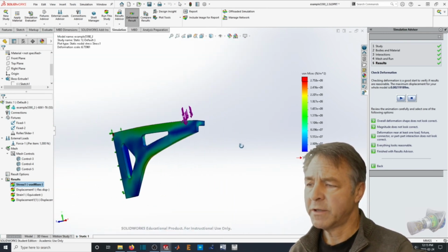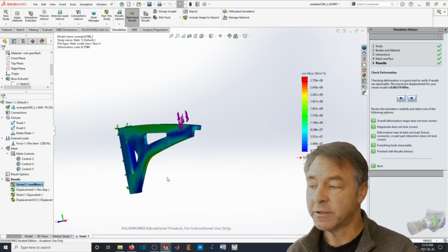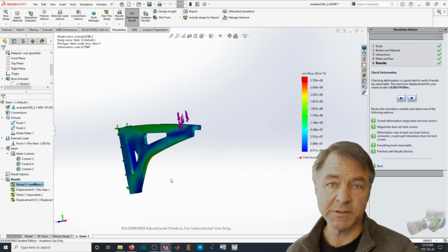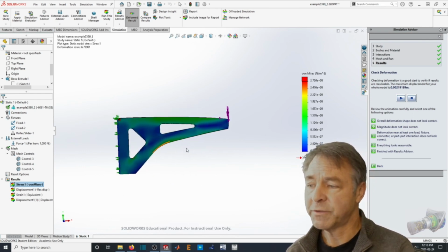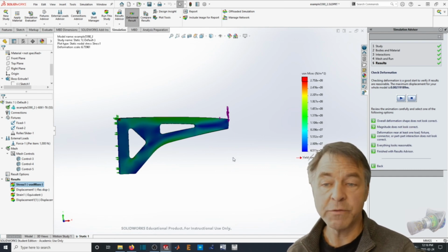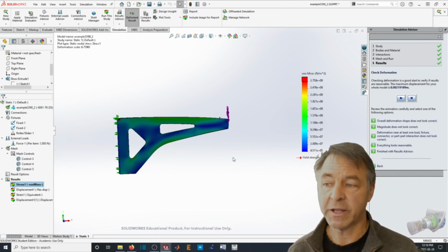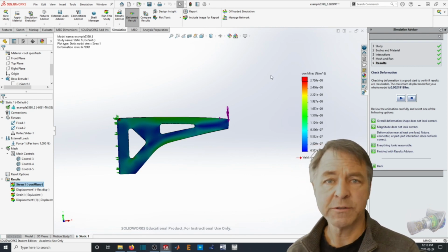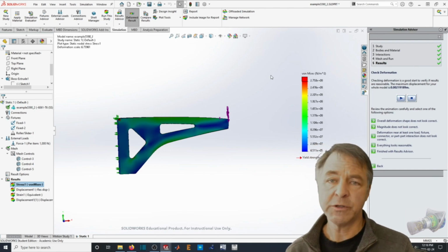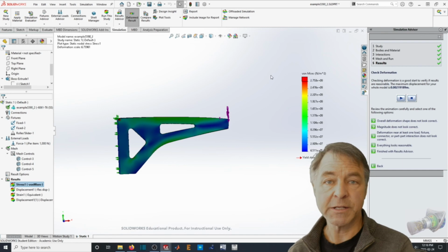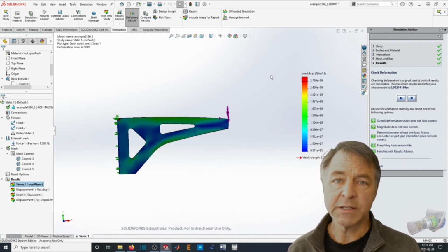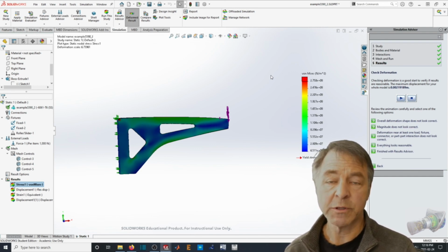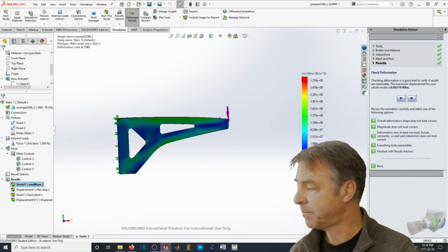And we've made a part that compared to where we started is almost insignificantly different in the cost and the design, and yet in terms of its functionality significantly improved. We've gone from 2.8 millimeter deflection at load to 2.2 millimeters for no cost. So this is what the value you can get from doing finite element modeling as part of your design is all about. It's not about coming up with pretty pictures. It's about using the finite element modeling tool to actually help you improve your design.